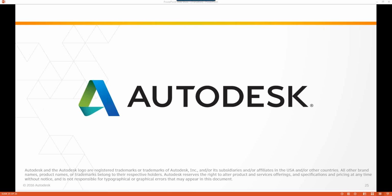So there's a little bit of a gray area. We've been taught in school that hex elements are always going to be better than tets, that you're going to get better results for fewer element count. But the thing that's changed over the last couple of years is the performance that we've got on specifically TET10 elements. So the balance is kind of right in the middle there.